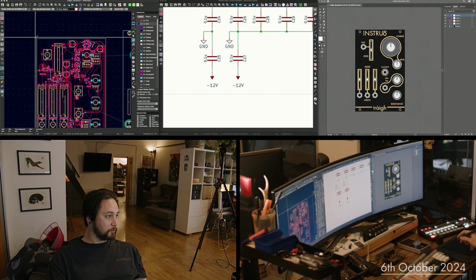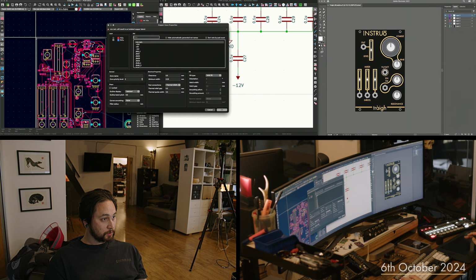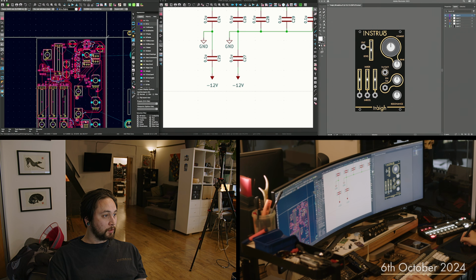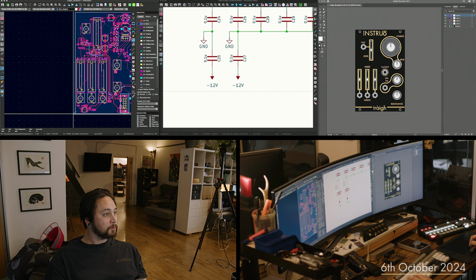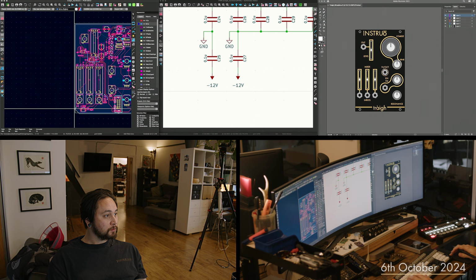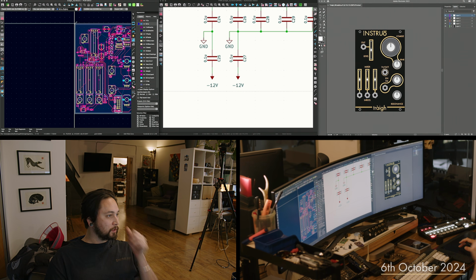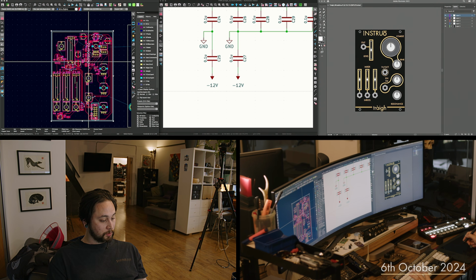Okay, so I want to do this. Set point option Z. Ground. Okay. And then I'm just drawing the outline around the PCB. It will only fill within the PCB dimension, which is fine. Trying to get a perfect rectangle, no weird extra vectors in it. There we go. And B is fill.